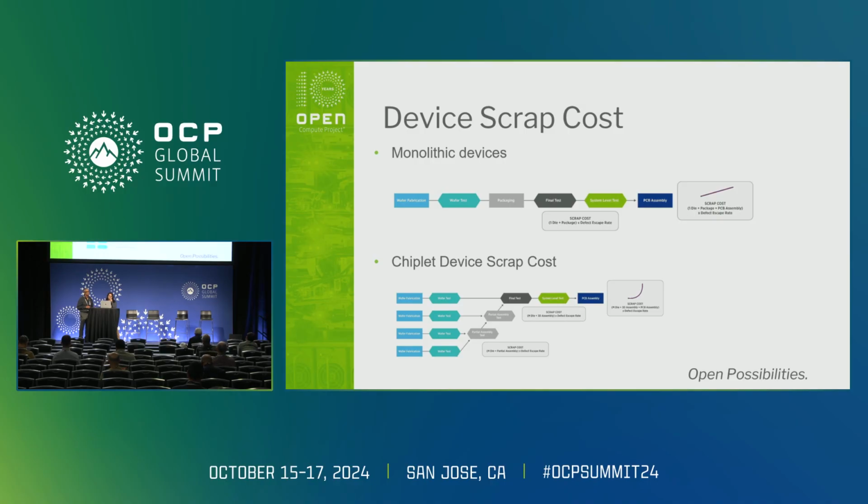And the expenses that are linked to conventional monolithic devices show a very linear trend when we go from fabrication to packaging to assembly, while in multi-die systems these show an exponential trend going from fabrication, packaging, and assembly. The paper does talk about some techniques where, by shifting focus to early and later stages of the manufacturing cycle, economic feasibility of the package can be achieved. Over to Rajesh for more on test standards.